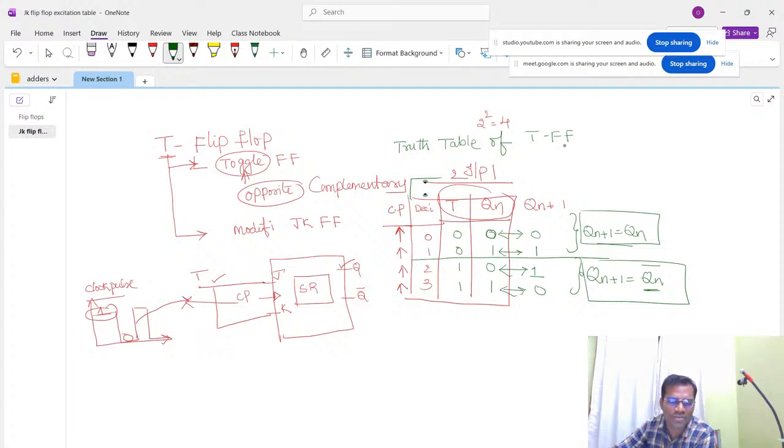Why is it called toggle? One output is Qn and another output is Qn bar. So both Q and Qn bar are of which nature? Opposite in nature. This opposite nature is technically called toggle. Whenever these are opposite in nature, they are also called complementary. Both the outputs are complementary, which means this is going to have two stable states.